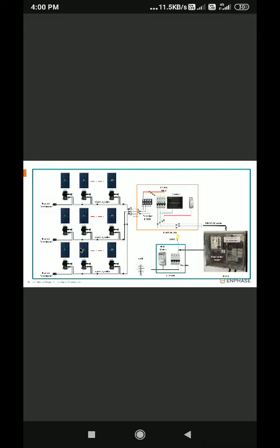So here it is 13. So 13 is the higher size that we'll see at the later stage. You can design the string sizes based on the site requirements also. So all the three phases you connect to an MCB, a 4-pole MCB, where you feed the three-phase wire by using a 4-core wire. You feed the three-phase grid supply.